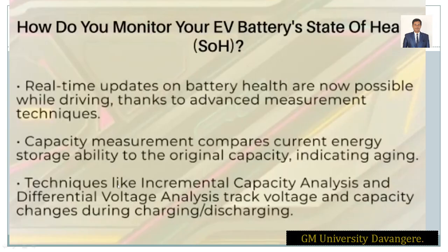Okay. So for the capacity measurement, as I told you, we measure the various parameters: the current, the voltage, and the storage capacity with respect to the original capacity. That will indicate the aging factor also. In capacity measurement, we see how much charge has been stored and how much energy has been retained, the remaining energy. That is what you have to think about for SOH. That is the capacity measurement.